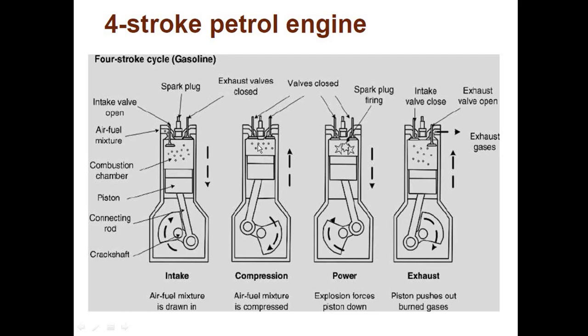Similarly, in the combustion stroke, heat generation also occurs as a constant volume process, meaning it maintains the clearance volume inside the combustion chamber. Constant volume heat addition occurs, and constant volume heat rejection occurs during the exhaust stroke. At the initiation of the exhaust stroke, when the piston is at bottom dead center, there will be a sudden heat transfer from the cylinder to the exhaust valve, and after that the piston will move from bottom dead center to top dead center.